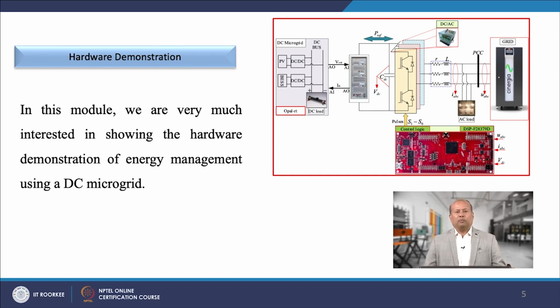The output of the power amplifier is connected to the IGBT stack at the DC input side. The output side of the IGBT stack is connected to an MCB, which forms an AC bus at which the AC load is connected in parallel to the grid.